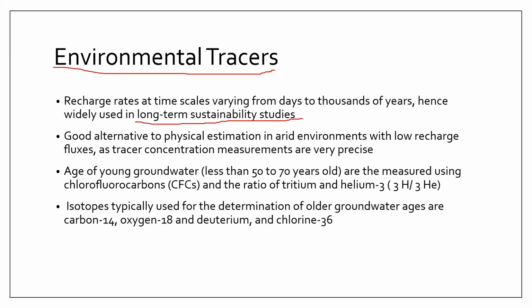Okay, so what's the practical implication of this? I mean, who cares if the water is 1,000 years old? Well, the practical implication is that it took a very long time for that groundwater to reach that depth. Okay, and it means that you are probably looking at thousands of years before that groundwater is actually replenished. So it's really ideal to avoid extracting water from really, really old aquifers because they take a lot of time to replenish and you might be depleting them by getting water from them. I mean, the term is mining water from them.